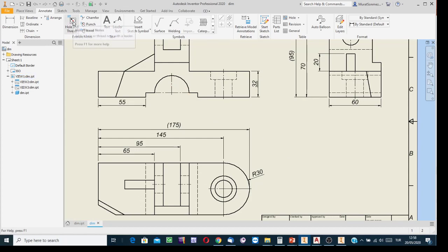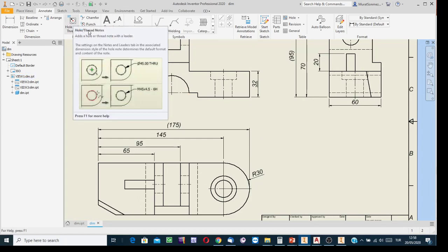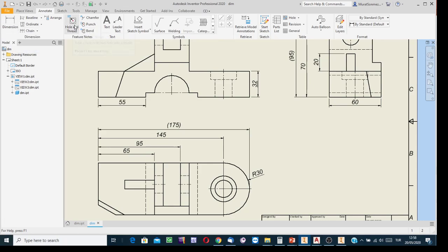Clicked on the hole specification indication button, not dimensioning but hole, not leader line but hole, this option. And then see the magic, indicate after that the edge of the hole with a click, and then move the cursor, click, that's it. Well, the annotation data will be gathered from the solid model and the necessary annotation will be written by the software. Quite convenient.